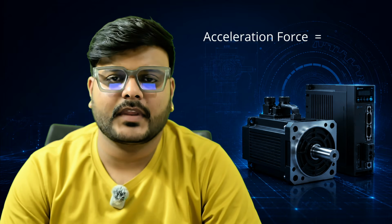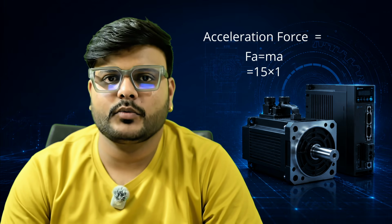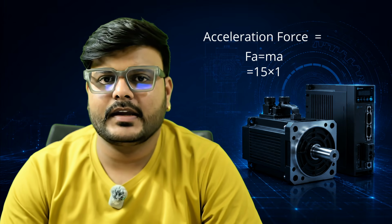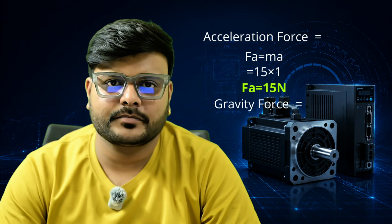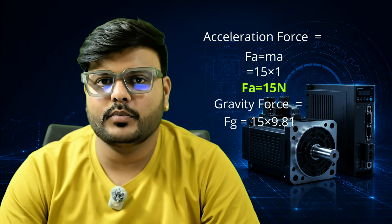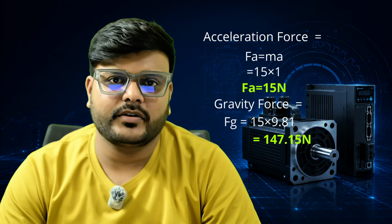Next step is acceleration force. We know the formula F equals m a. Our total moving mass is 15 kg and our acceleration is 1 meter per second square. So we get an acceleration force of 15 Newton. Gravity force means total weight multiplied by gravity, and the gravity value is 9.81. So 15 multiplied by 9.81, we get 147.15 Newton.